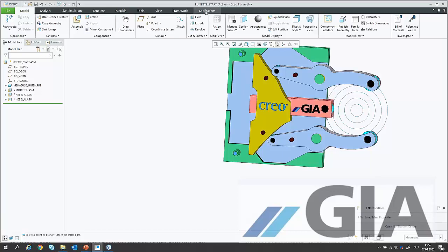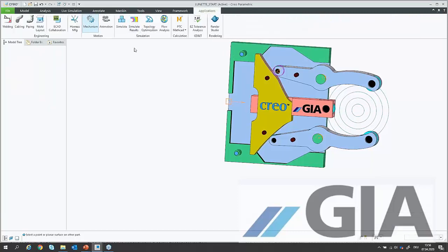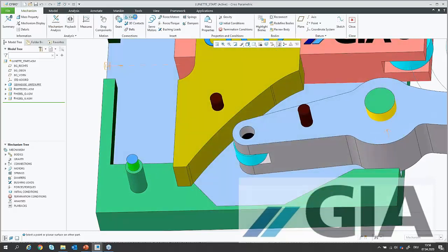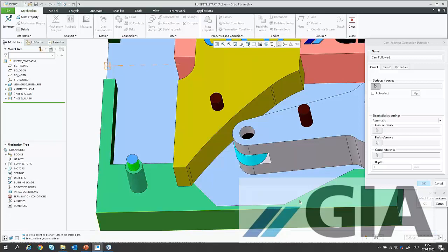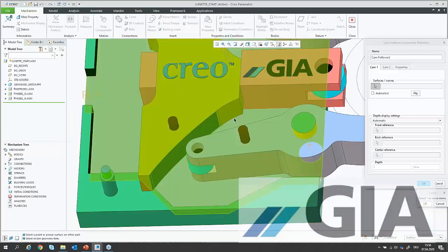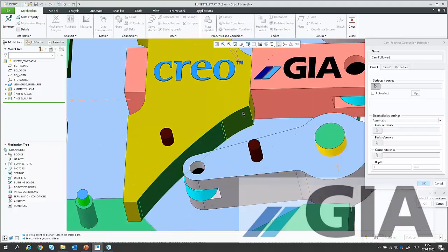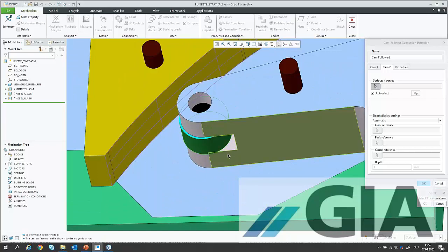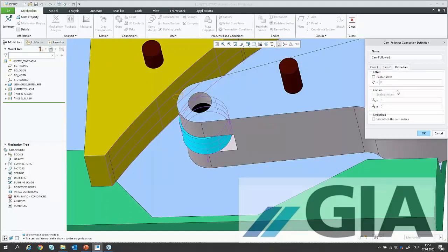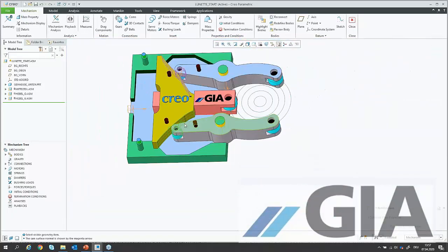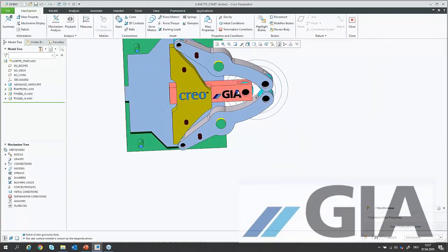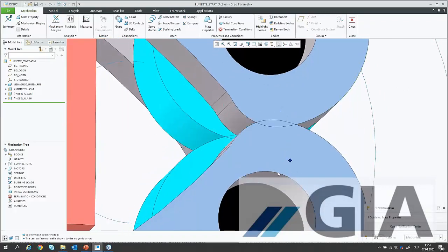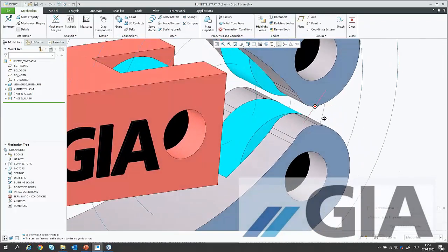Going back here again, maybe for mechanism, in order to connect this cam here. Using again maybe only the surfaces, this, control, this. Middle mouse button should be connected to this cylindrical surface. And because liftoff is not enabled, it connects, and then I can see the behavior here. And here we can see, okay, we're getting an interference, and I can also use, let's say, this cam connection